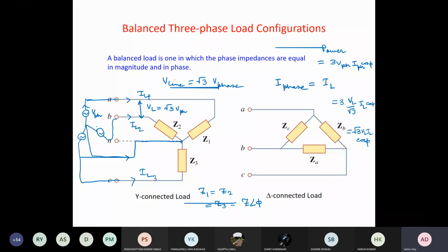So this is actually a three phase 4 wire system, which we'll discuss later. The neutral line helps the unequal line currents. Sir, is the sum equal to zero? No, it will not be equal to 0. It will pass through here, but the potential has to be maintained here at 0. Okay. So if we do not do that, then your potential will change and it will no longer be a balanced three phase like this. There will be a polarity like this.